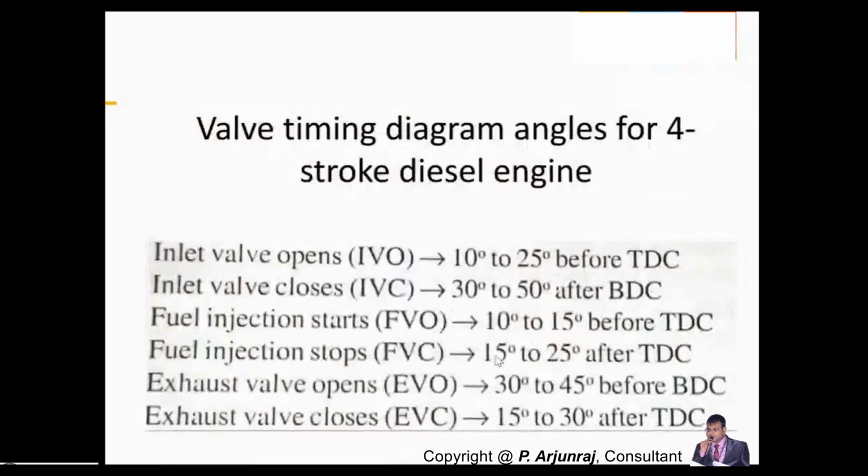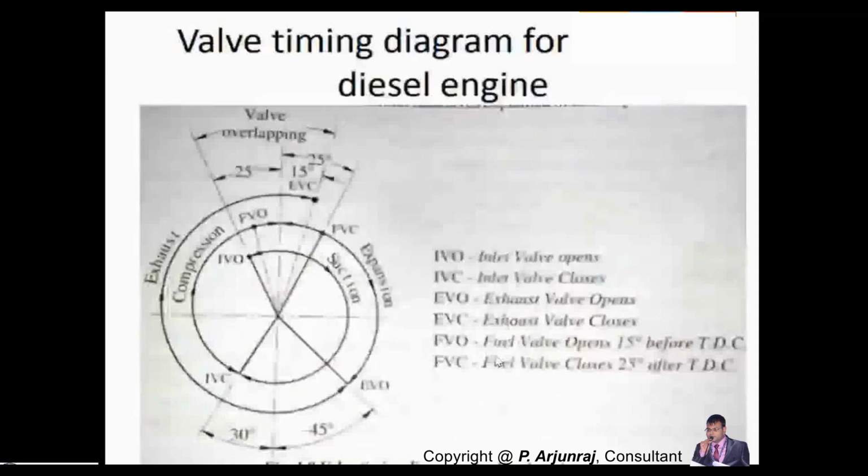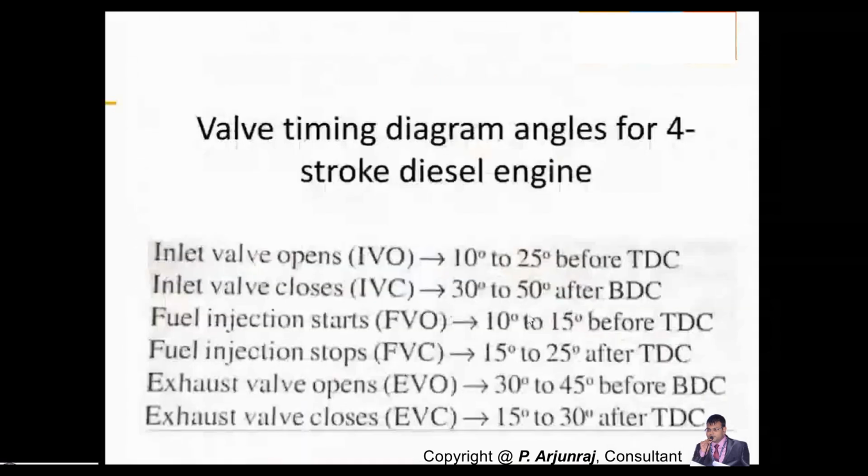This is the overview. When I say the values here, it is not going to take place exactly at 10 degrees or exactly at 25 degrees. It will vary depending upon the engine configuration. So just to give you an overview, the inlet valve opens in the case of a four-stroke diesel engine 10 to 15, 25 degrees before top dead center.